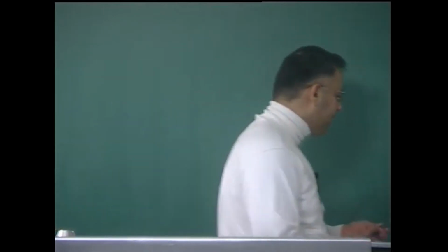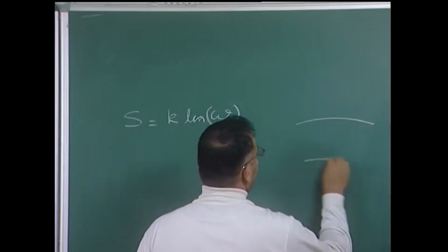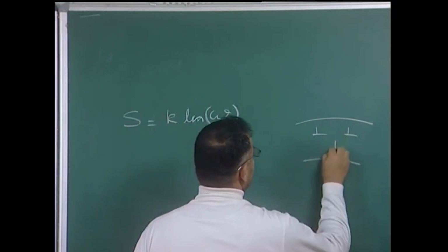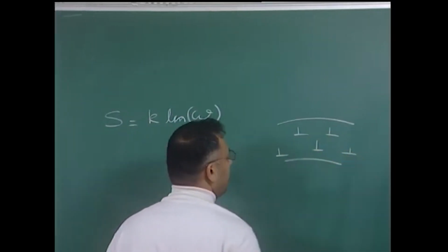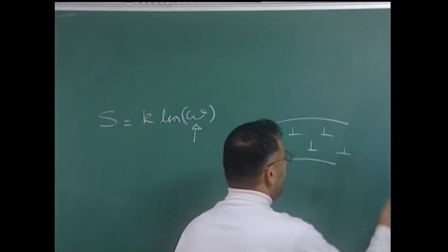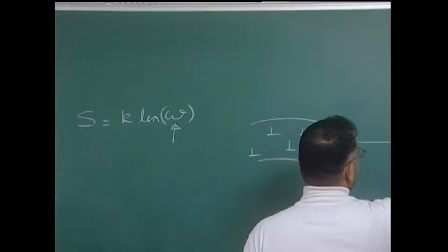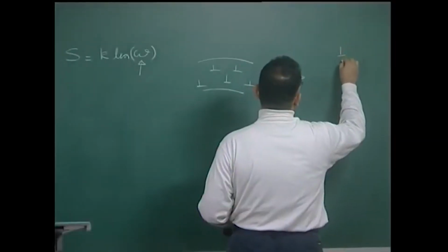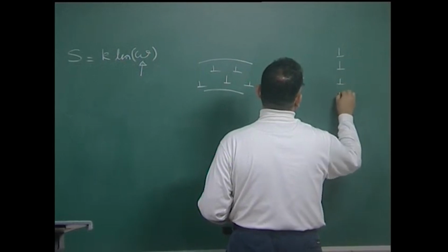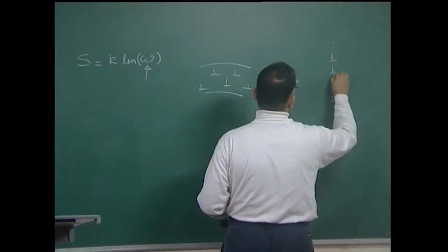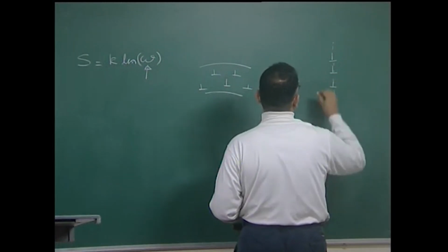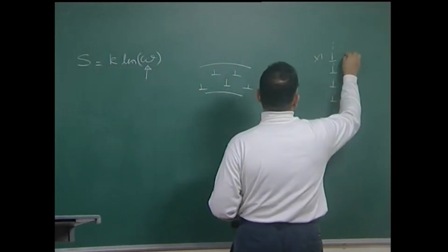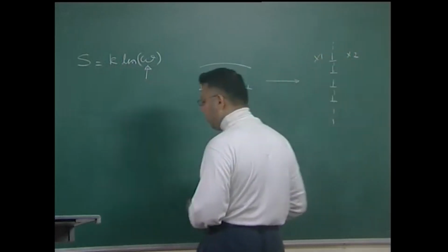So, let me redraw that schematic for you. Originally we had considered that in a bent crystal there are these statistically stored dislocations. These dislocations may move in the presence of thermal activation to form a low angle grain boundary, which is nothing but an array of dislocations. This is my low angle grain boundary, and therefore, crystal 1 and crystal 2 are misoriented. So, this is some sort of a sub grain boundary.